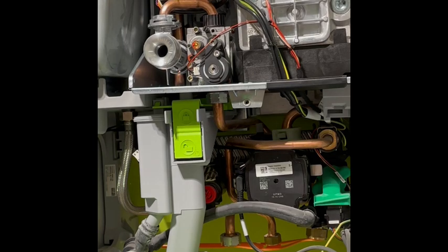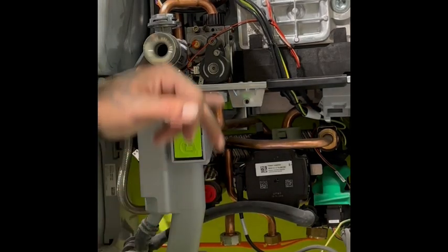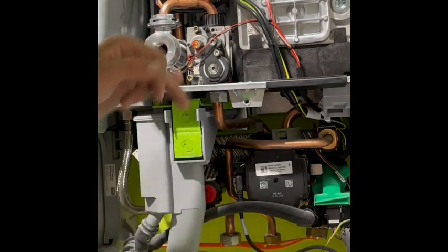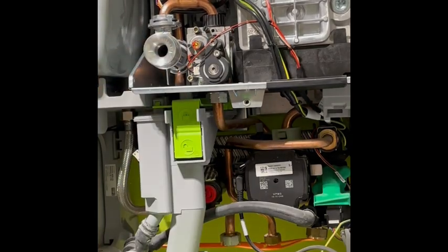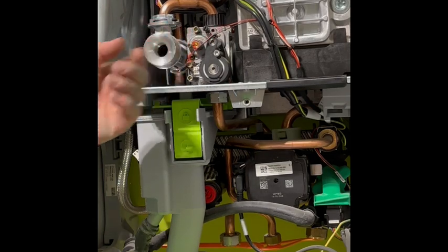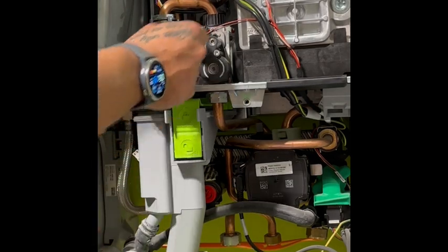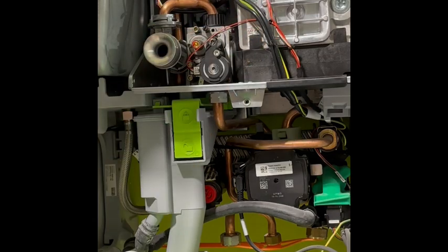different. Some gas valves are easy to get to and take a reading. Some are more difficult, and sometimes you have to take a reading from the circuit board itself. However, personally, I always try and get my reading from the gas valve itself, because it proves that my harness is okay as well.